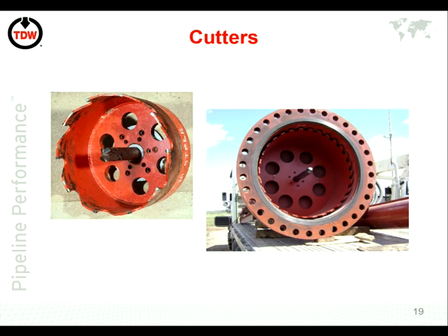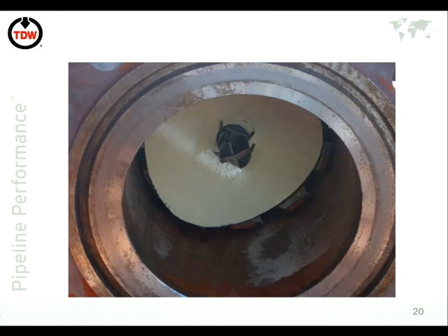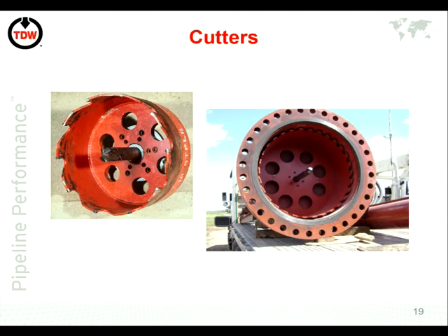Regarding this cutter, do you have 3 millimeters? No, the smallest one we do is 1/2 inch, so that would be 12.7. But a 12.7 will just be a drill. It won't be a cutter. I think it's about 2 inch where you start moving from a drill to a cutter, primarily because you can't have a drill which is this diameter. You're really limited by the diameter of the drill, and that's when you transition to the cutter itself.